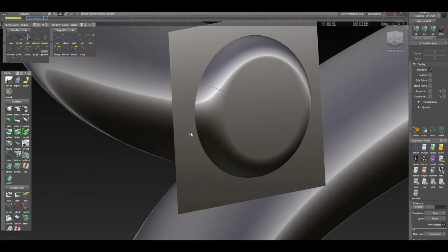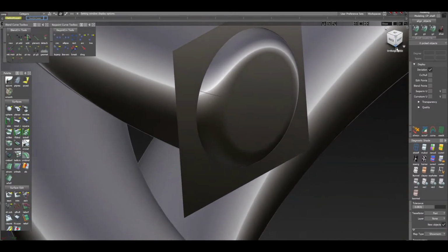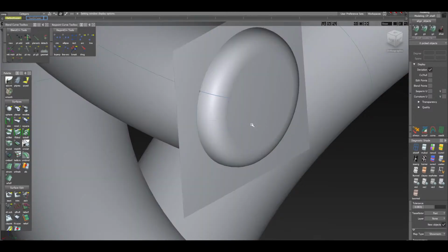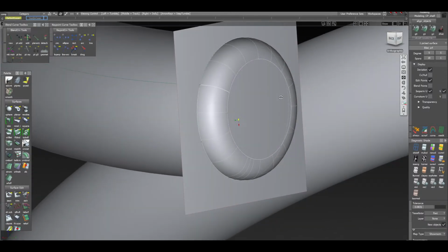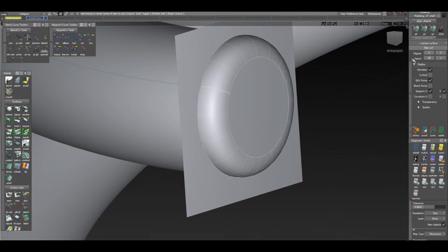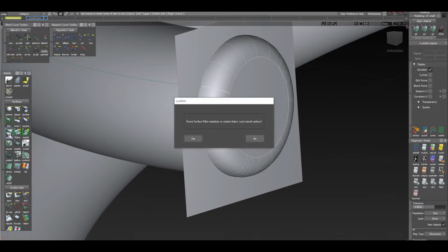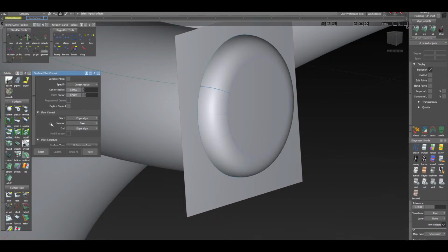Take note, however, that while deleting the curve on surface data, I think we've deleted the construction history for our fillet, okay? And I'm just going to verify that right now. And we have. So we can't edit the parameters right now for our fillet. It's a bit of a bummer because if we wanted to reduce our spans and stuff here, there would be some functions and ways for us to do that. There are ways that we can still do everything that we did without deleting construction history. I just deleted construction history because I wanted it to be fast.